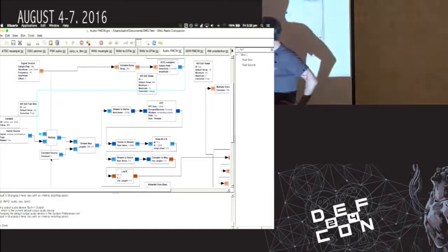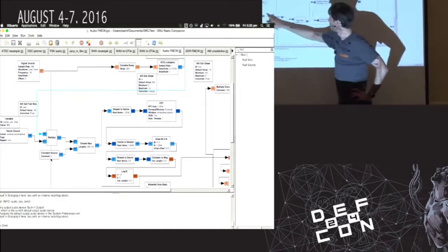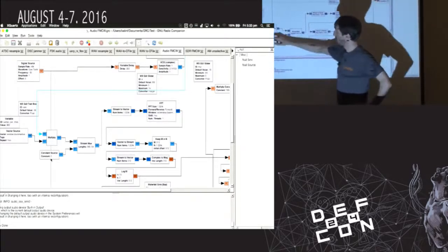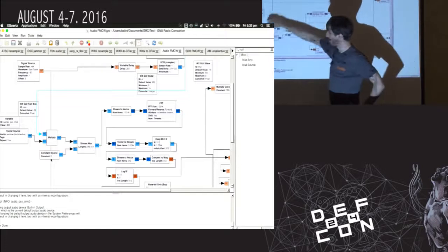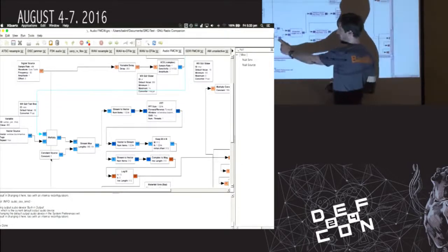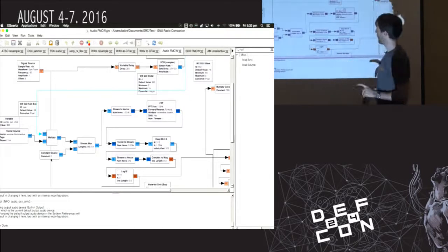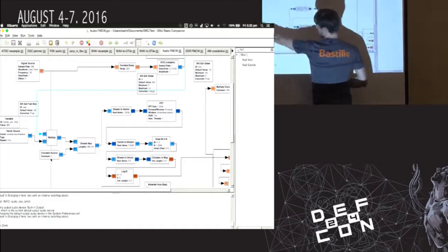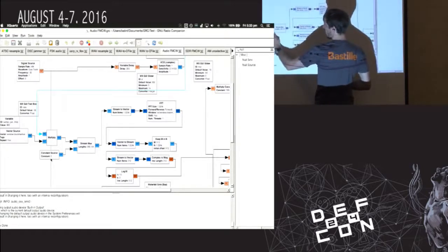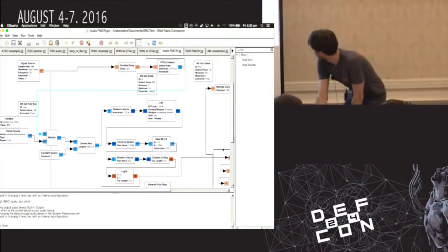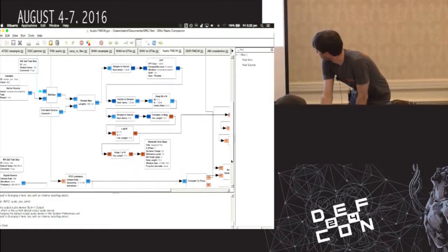So here, I basically have a window. Usually the window is applied within the FFT block, but here I window the samples that I've received, which are shorter than 1024, and then I'm padding the rest out with zeros, so I'm effectively bringing it up to power of 2. And then the stream mux is combining the samples that I've brought in and windowed with the padding on the end, and then it's going into the FFT. So that works too.